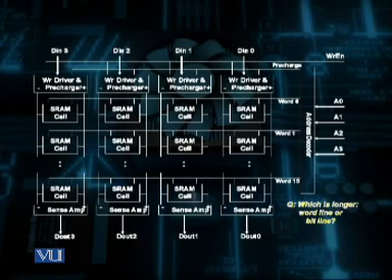Here you can see that in this picture the 16 words and 4 bits are arranged in an array form. The word lines are connected horizontally to the address decoder, while the bit lines are connected vertically to the sense amplifiers and write drivers.